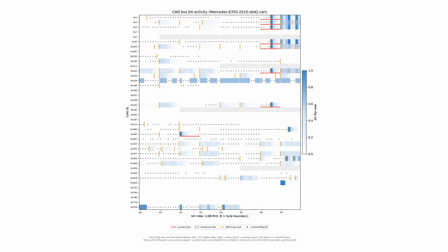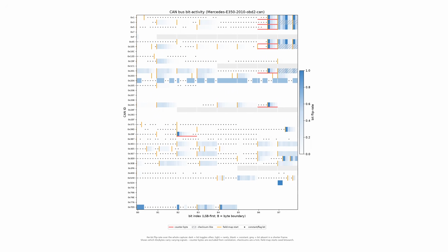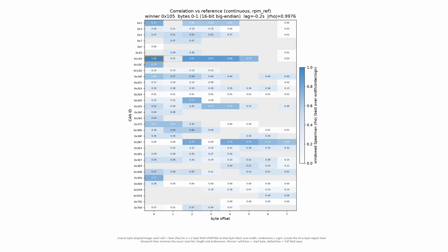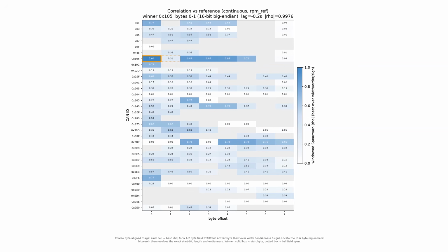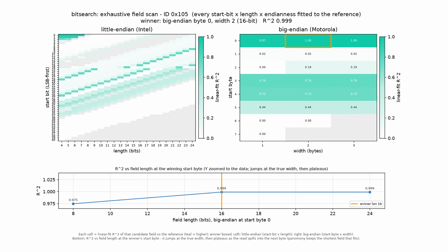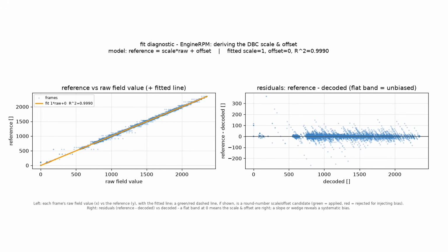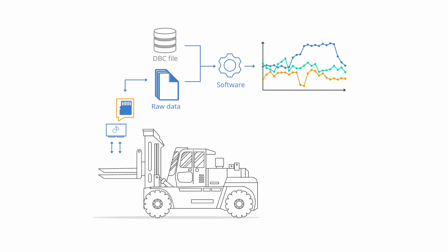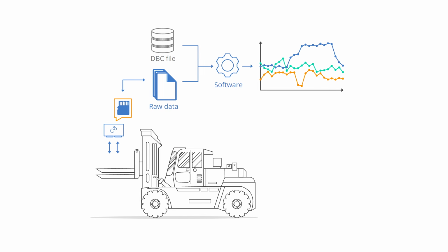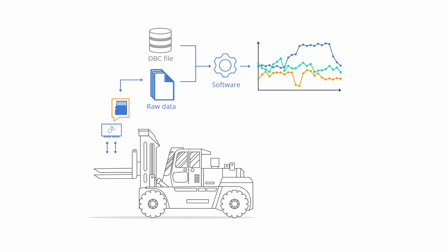But once you give Claude the reference data, as well as the raw CAN bus data, it goes through a number of analysis steps, doing statistical analysis, surfacing what are the correlated target potential candidates for your signal. And based on this and doing a number of different steps that I'll cover in a moment, it is able to get to a conclusion in almost all of the cases that I have tested where it has detected the relevant underlying proprietary signal correctly, and it will then create a DBC file based on this result that you can directly use to decode your data in tools like webCAN.